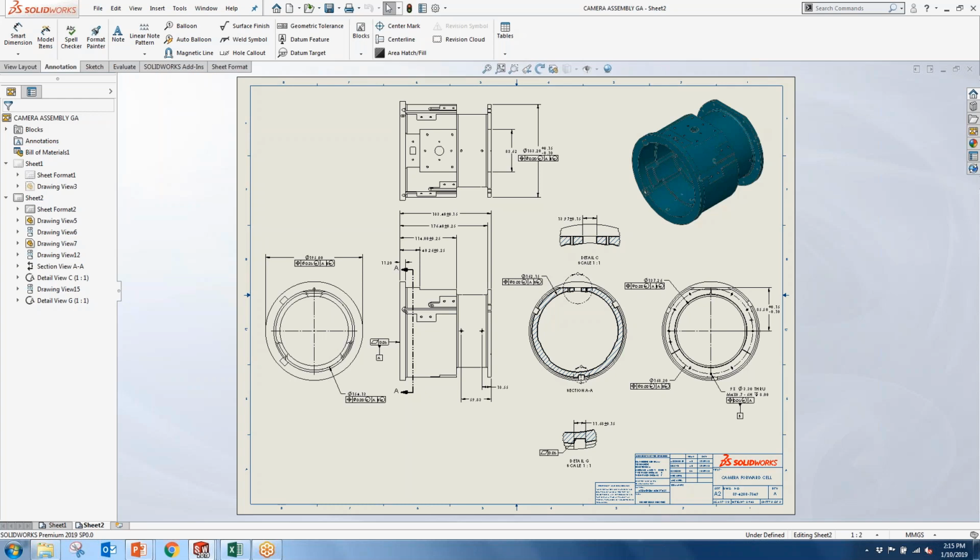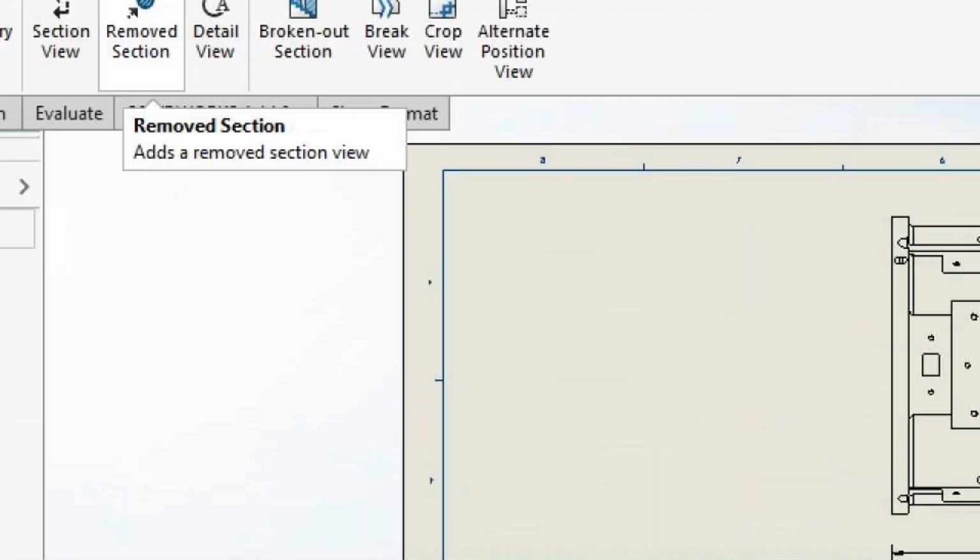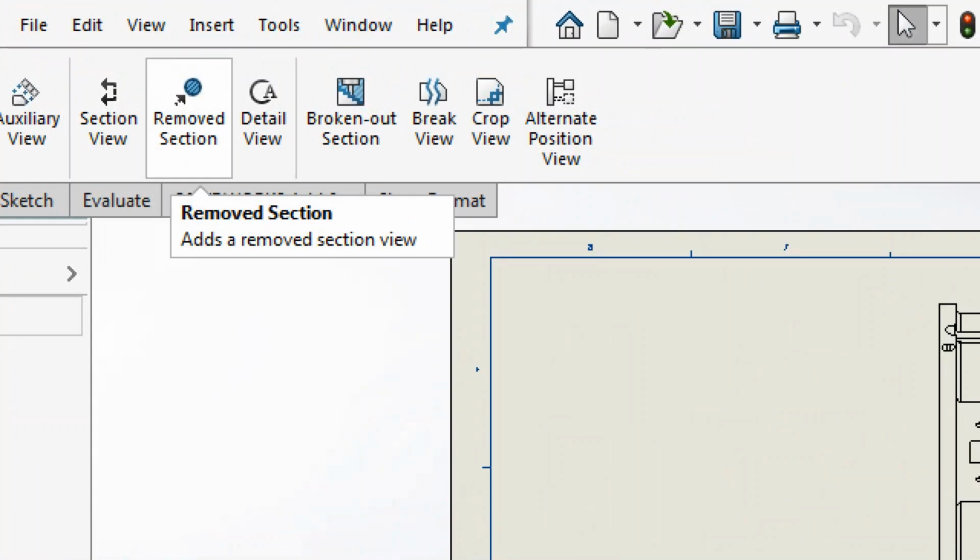Second one is kind of validating and doing the rebuild, and then the last one is just rendering everything out. Pretty much, unless you have a really large or performance intensive drawing, most of that is kind of negligible to the eyes. So here we have our drawing, and we need to create a section view for this view down here.